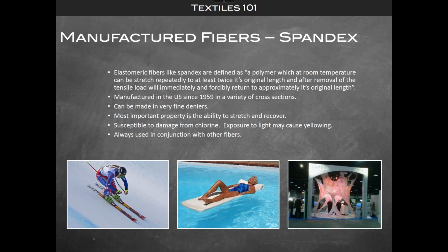The last manufactured fiber that we'll talk about today is spandex. Spandex is an elastomeric fiber, and the definition of an elastomeric fiber is a polymer which at room temperature can be stretched repeatedly to at least twice its original length, and after removal of the tensile load will immediately and forcibly return to approximately its original length. So basically this is saying an elastomeric fiber is defined as something that you can stretch over and over again, and it will recover back to its original length.